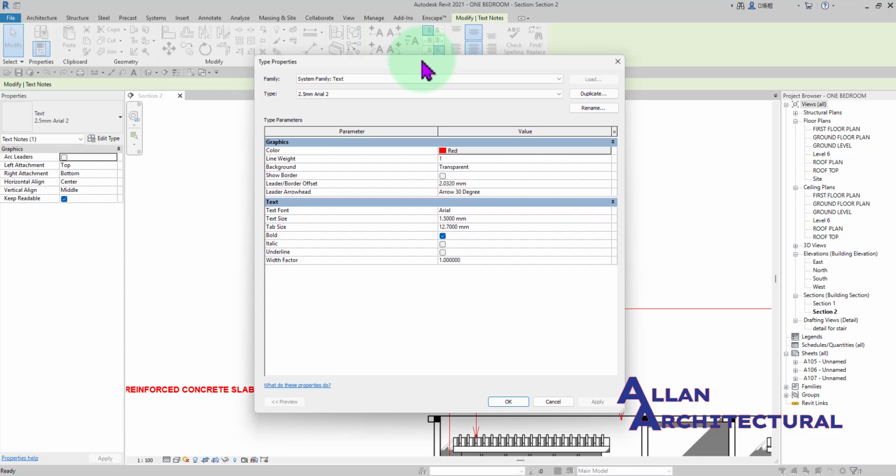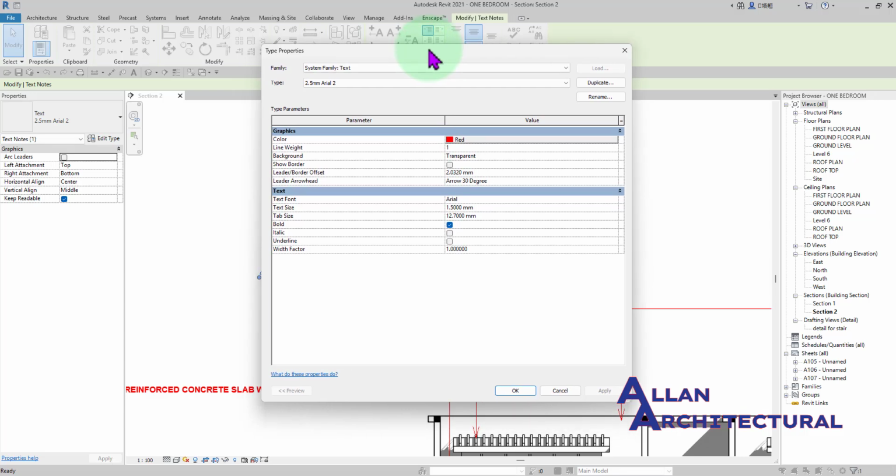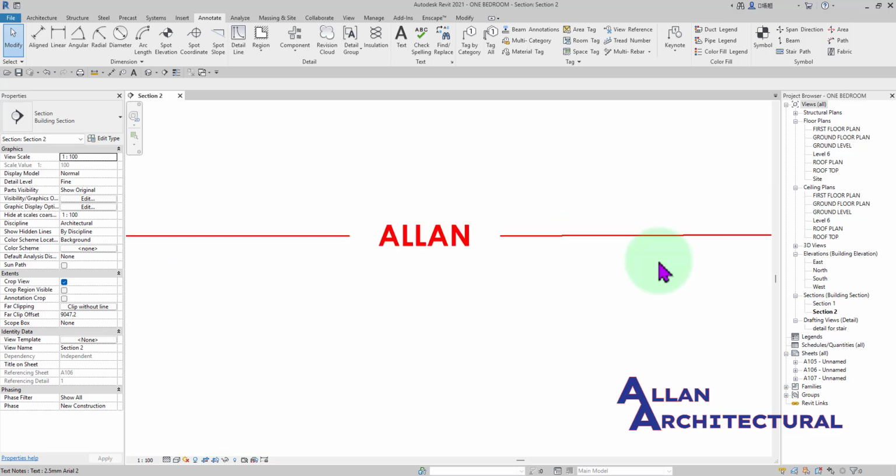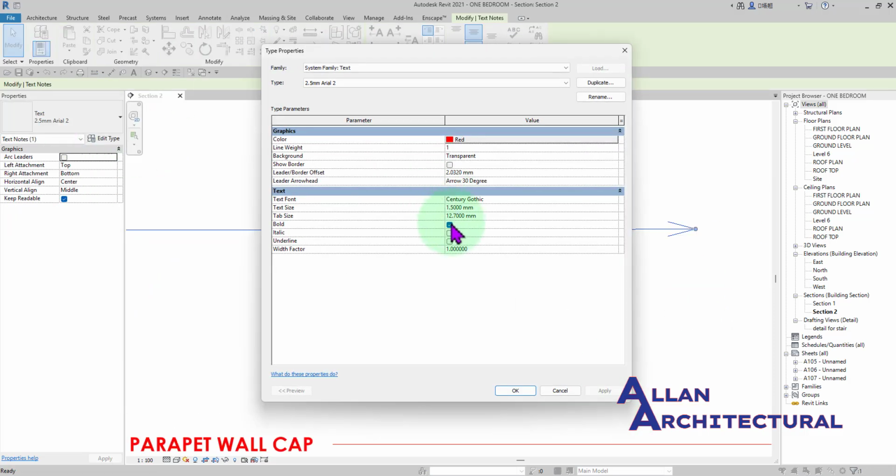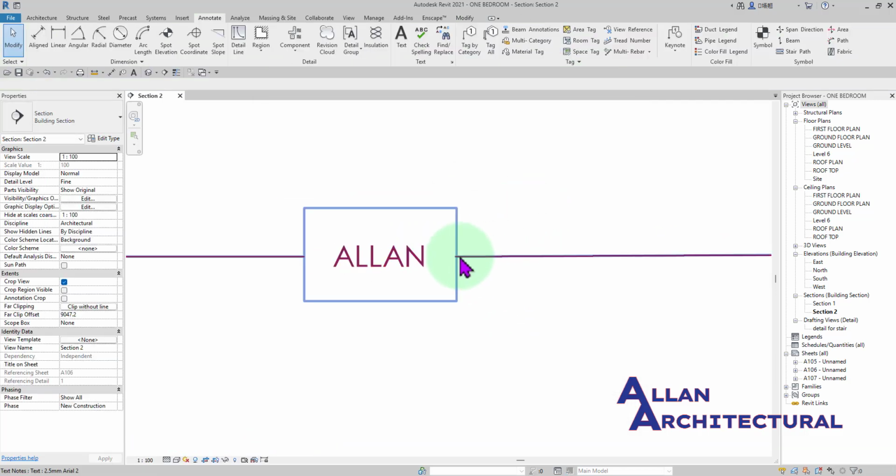And when you head into the edit type, like I said earlier in this video, I'm not going to assume my viewers out there understand what's happening in here. So with a text font style, you can actually change that. You can use any text font in there. So what my role model actually loves using is the Century Gothic, and you can make it bold. You can check or uncheck that if you want. Italic, you want it slanted, you can check this. If you want to underline, you can also check this, and that's what it is. So you can hit apply, hit OK, and we have this in here, right? So I can get back in here, check the bold and click on OK. So we have this in here.